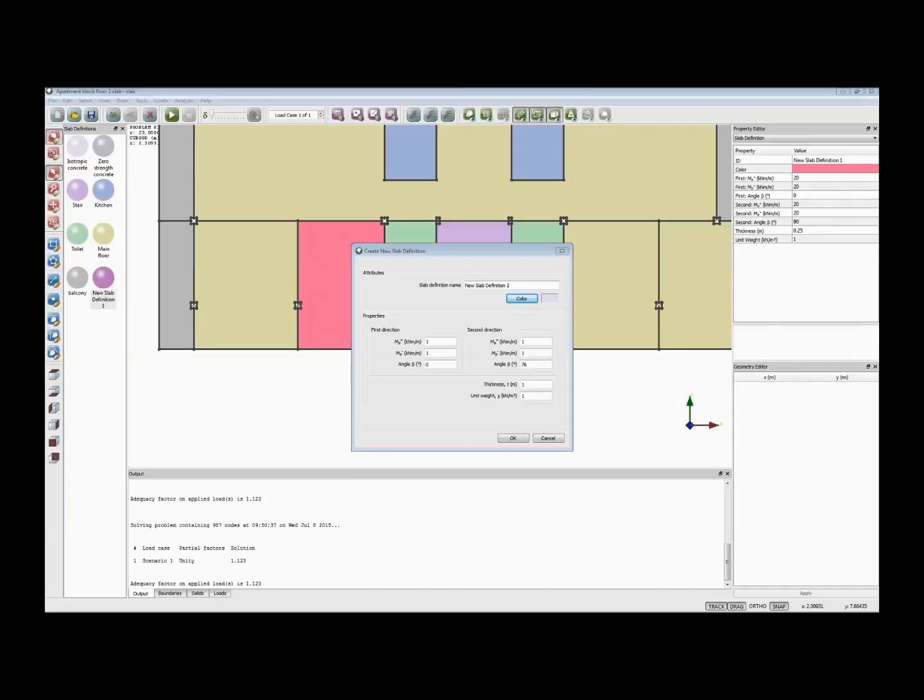You know what the reinforcement depth is, hopefully, either from drawings or from other investigations of your existing slab, and you can work out what a suitable plastic moment of resistance value is. So that's a fairly standard thing to do if anybody has dealt with the traditional hand-based yield line method, and it's available in any textbook on the subject.